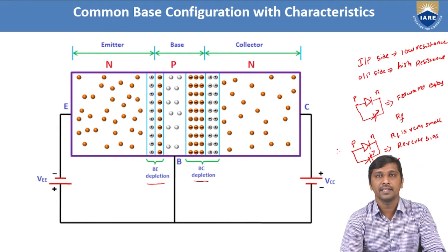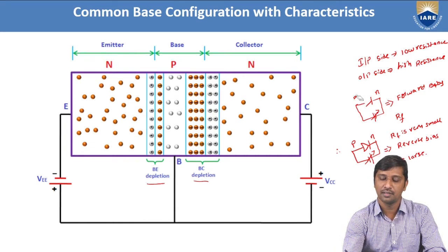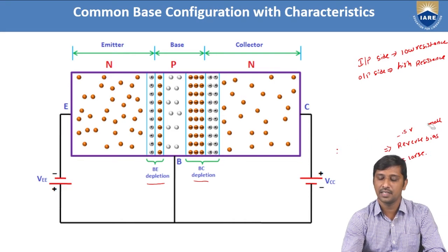Under reverse bias, no conduction takes place across the PN junction diode. That is the reason it offers very large reverse resistance. Hence RR is very large here. From these two observations, when the diode is forward biased, it offers very small forward resistance, and if the diode is operated under reverse bias, it offers very large reverse resistance.